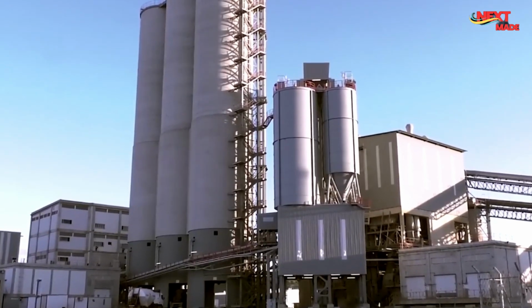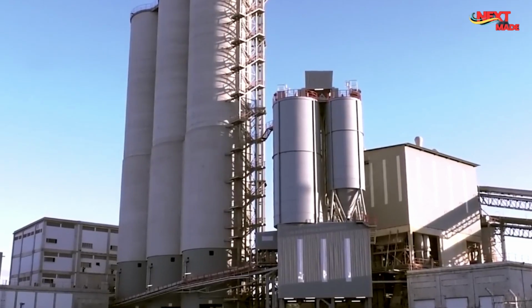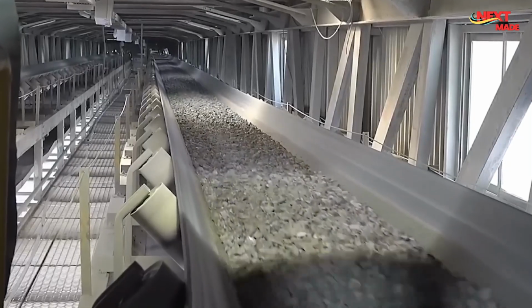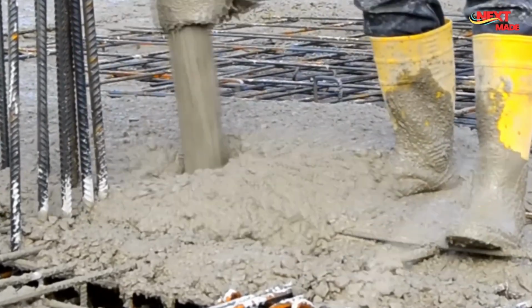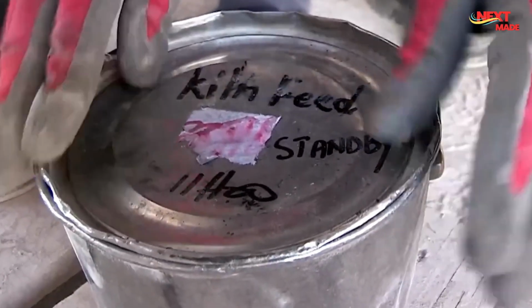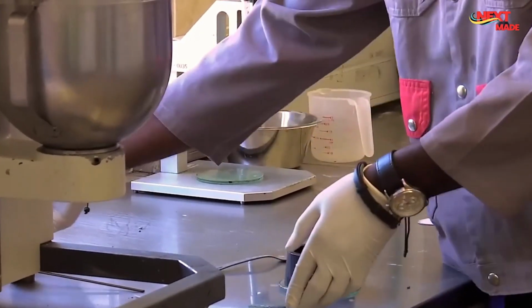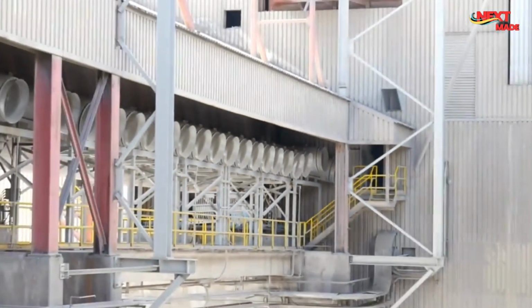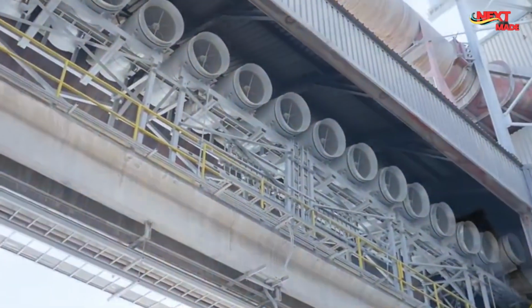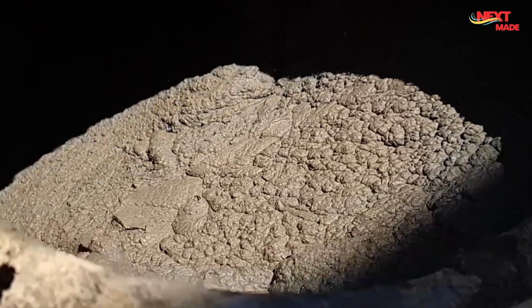Traditionally, this was done manually using shovels on a flat surface such as a concrete slab. However, nowadays, concrete mixers are commonly used, which automate and speed up the process. The mixing process ensures that the cement particles are evenly distributed throughout the aggregates. Once the dry ingredients are mixed, the water is added gradually while continuing to mix. When water and cement are mixed together, a paste called cement paste is formed. The hydration process generates heat and continues over an extended period, gradually increasing the strength and durability of the concrete. The mixing process continues until the concrete has a uniform consistency.